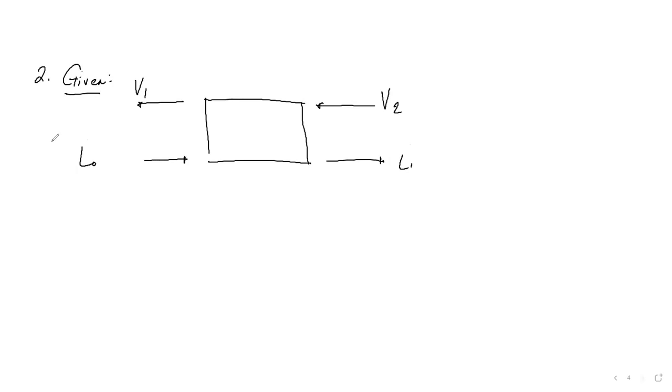You have 100 kilograms of soybeans containing 20 weight percent oil. So in your 100 kilograms, if 20% is oil, then you have 20 kilograms A, and the rest would be your B. Okay, so in the statement, it says that it's going to be leached with 100 kilograms of fresh solvent. So this one, 100 kilograms C. Okay, it's all C.